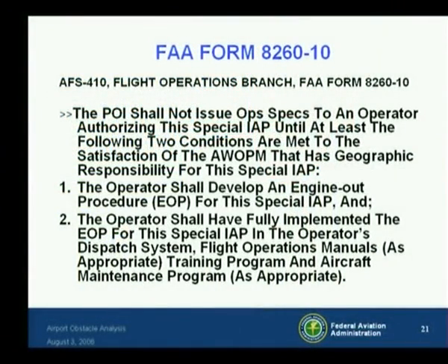The FAA does. The POI shall not issue op specs to an operator authorizing this special instrument approach procedure until at least the following two conditions are met to the satisfaction of the All-Weather Operations Program Manager, or AWO, that has geographic responsibility for this special IAP. The operator shall develop an engine-out procedure for this special IAP, and the operator shall have fully implemented the EOP for this procedure in the dispatch system, flight operations manuals as appropriate, training program, and aircraft maintenance program as appropriate.